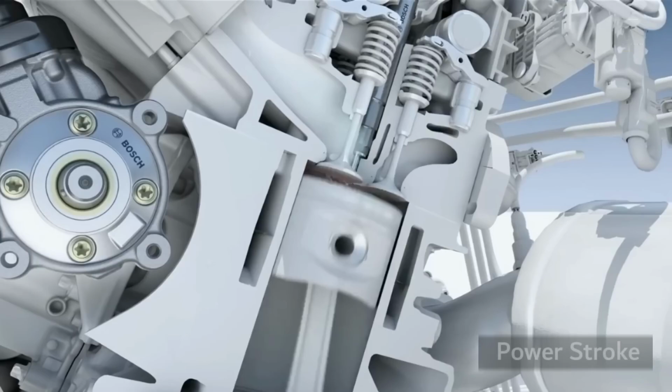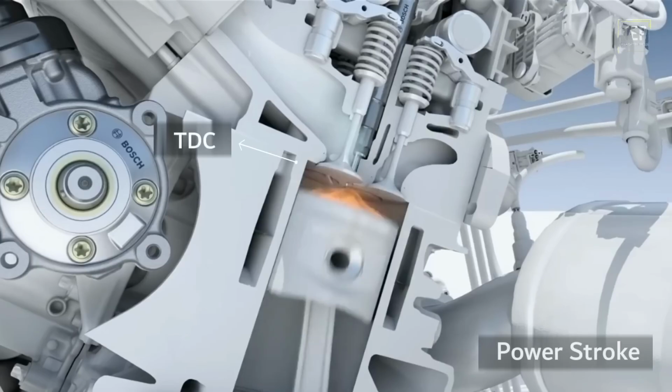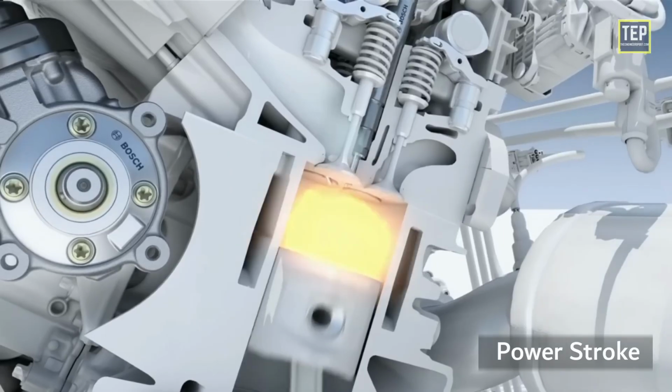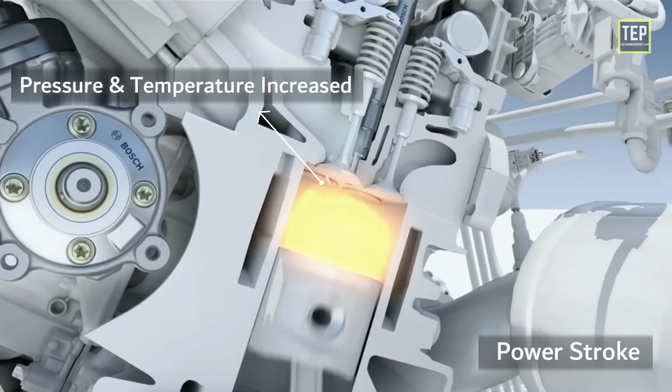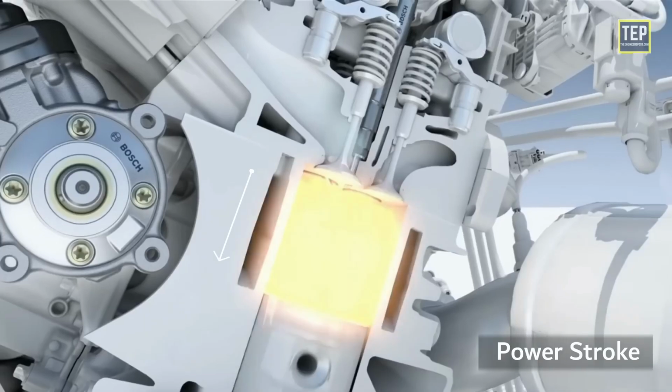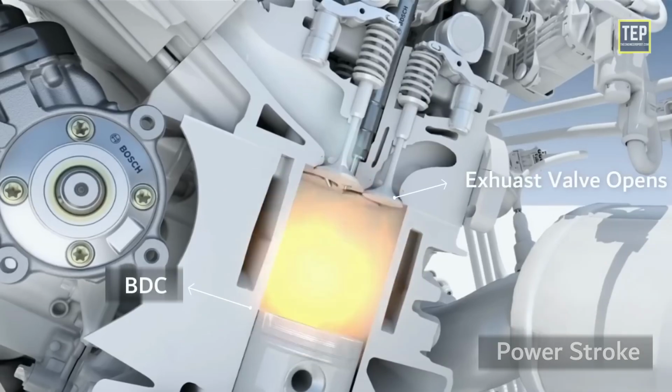Power stroke. The piston moves from top dead center to bottom dead center. The heat released by combustion increases the pressure and temperature of the air further. The maximum pressure and temperature of the burnt gases act on the top of the piston and force the piston to move fast, accelerating the piston downwards. Just before the piston reaches the bottom dead center, the exhaust valve opens.